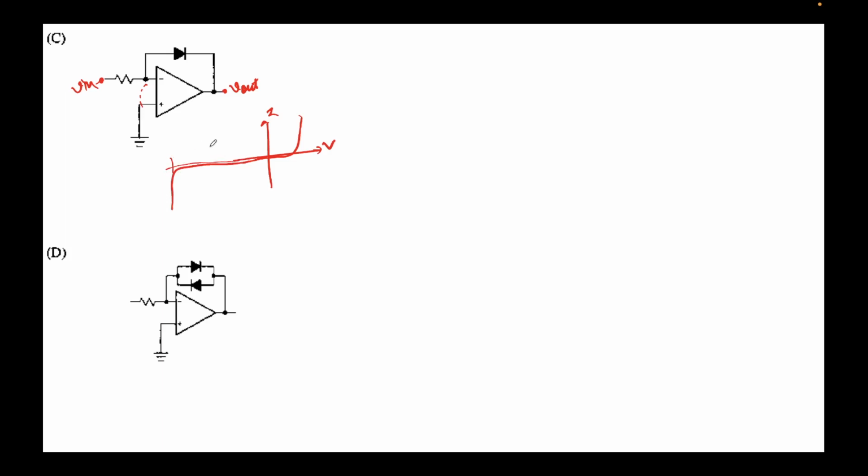So this is clearly much beyond the saturation voltage of the op amp. So again, let's do case 1 when V in is positive. Since the input is through the inverting terminal, the output will naturally be less than 0.